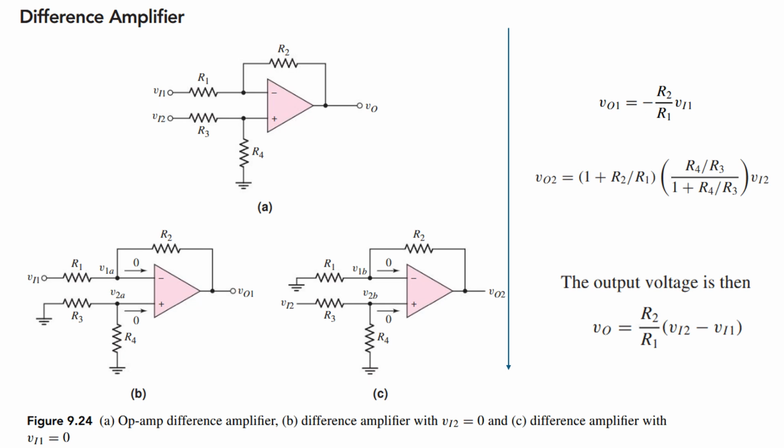So this is very simple to solve. Use only three conditions. The first is that the resistance between the minus and plus terminal must be infinity, and since the resistance is infinity between the minus and plus terminal, the voltage will be the same at the minus and plus terminal.